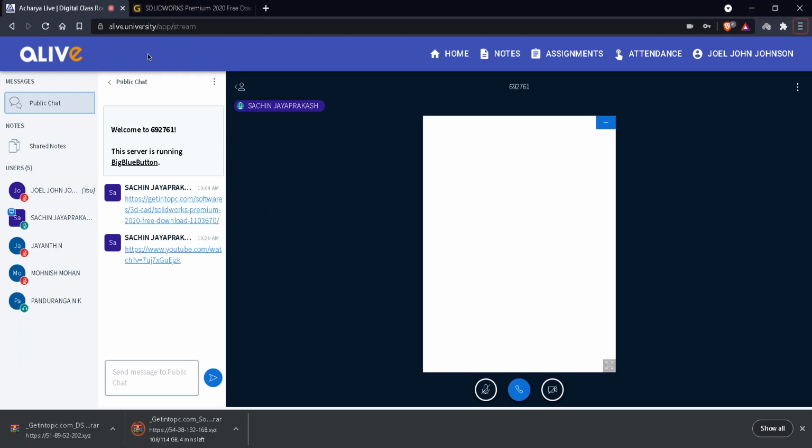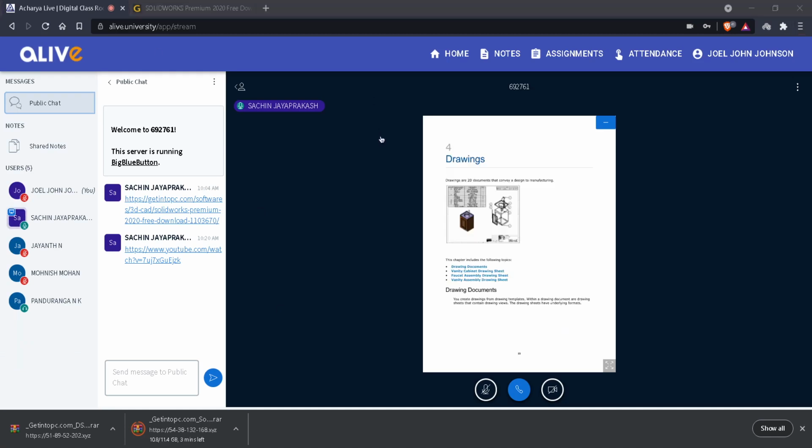And this is the drawing. You can choose whatever template you want based on drawing size: A2, A3, A1, A0, whatever paper size you want. Accordingly, if you have done the 3D already, the assembly or part, from that you can extract the actual 2D of it, and you can showcase your final 2D designs like this. This also we'll be doing after we do our assembly.